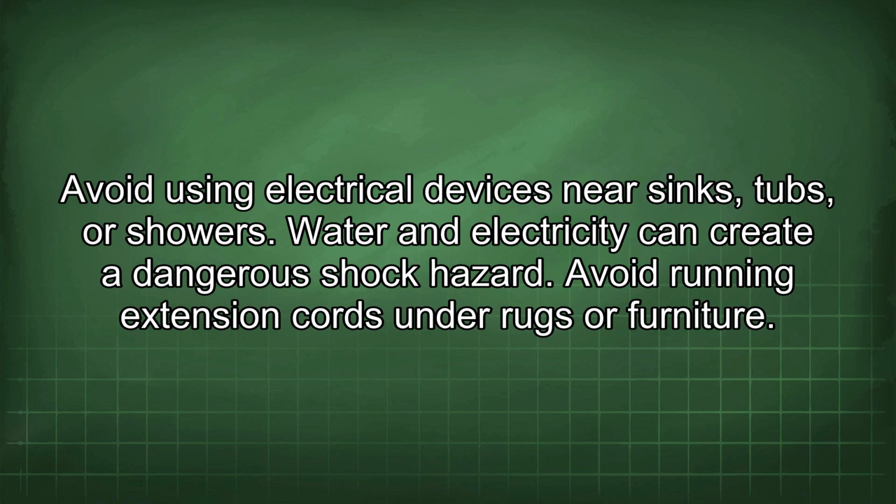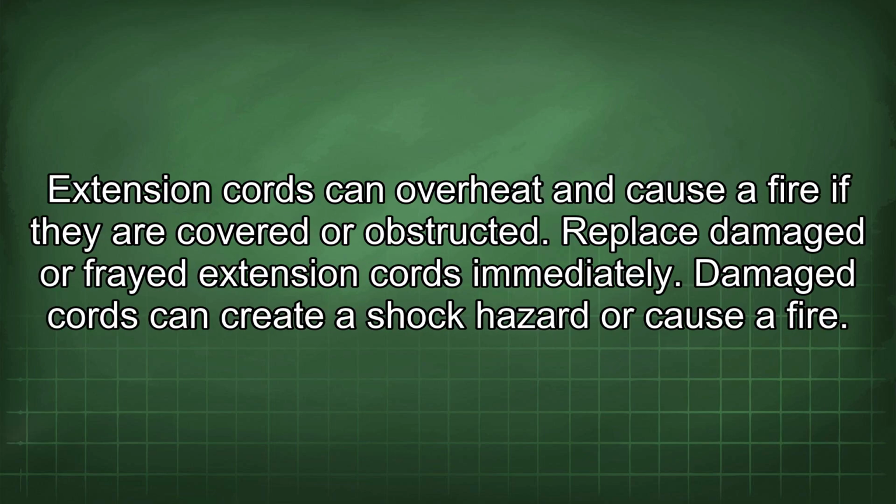Avoid running extension cords under rugs or furniture. Extension cords can overheat and cause a fire if they are covered or obstructed. Replace damaged or frayed extension cords immediately. Damaged cords can create a shock hazard or cause a fire.